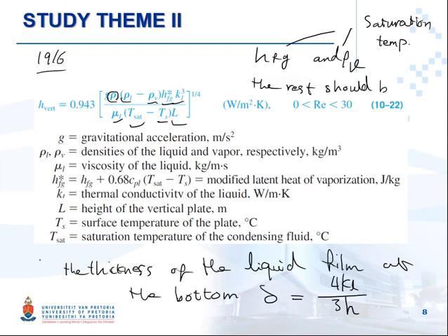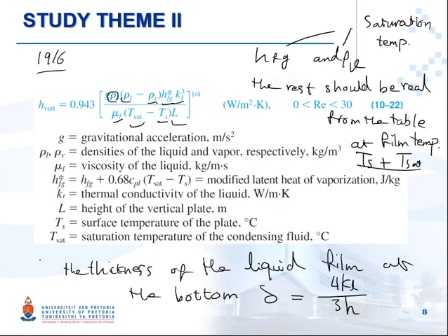The rest should be read from the table at film temperature. What is the film temperature? It is the surface temperature plus the saturation temperature divided by 2, the average of the two.